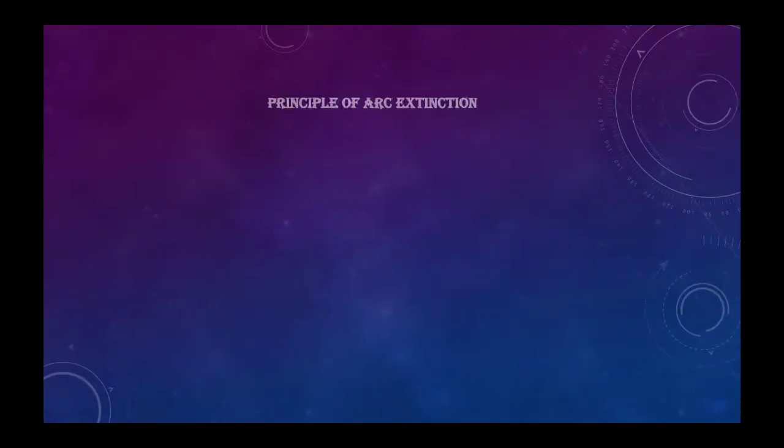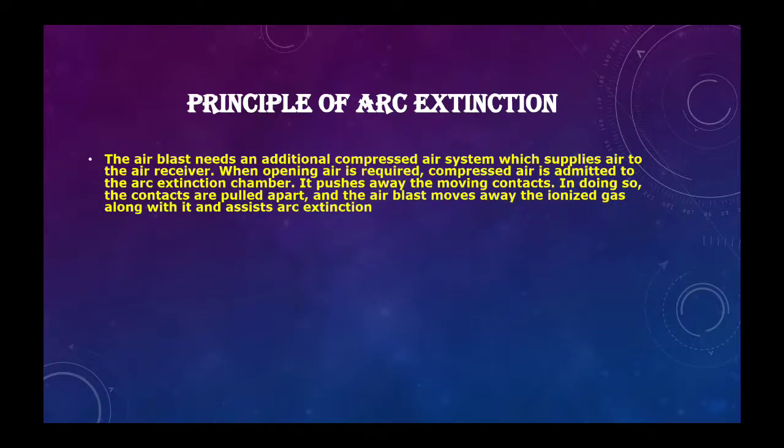And now the principle of arc extinction. The air blast needs an additional compressed air system which supplies air to the air reservoir. When opening air is required, compressed air is admitted to the arc extinction chamber. So the air blast system must need some compressed air for producing the blast effect.